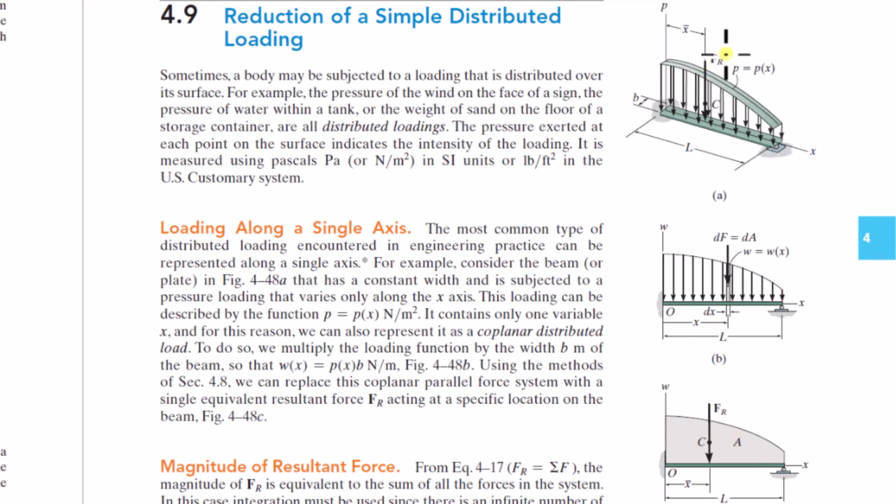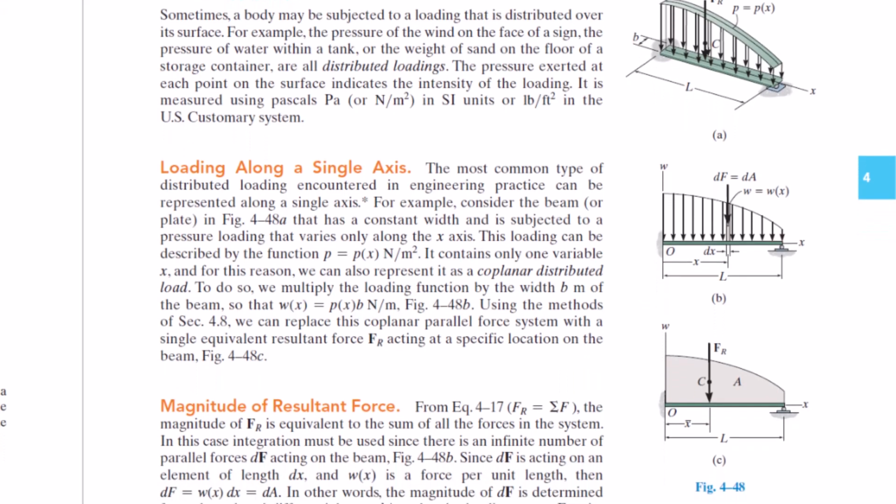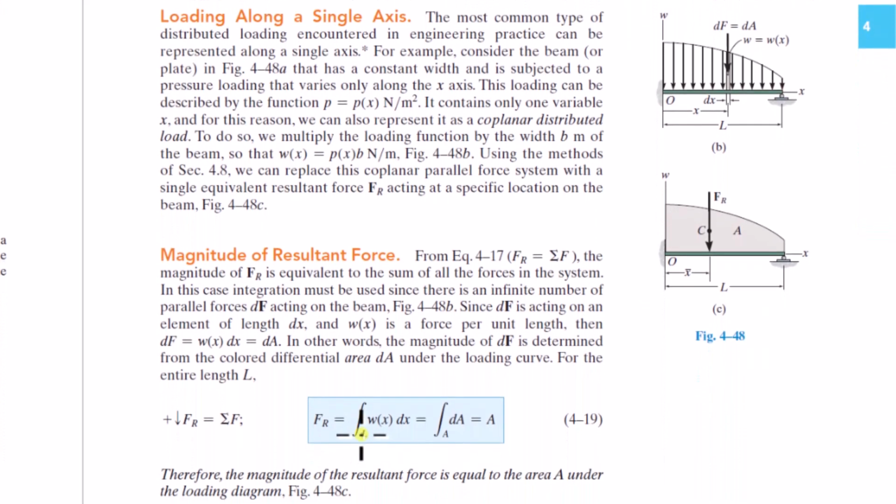It's the net force acting over that entire width at that point x. So that's dF. We just need to integrate from L to 0 dF. And that's what they do here, integrating across the length, w(x) dx. And then they call this A.